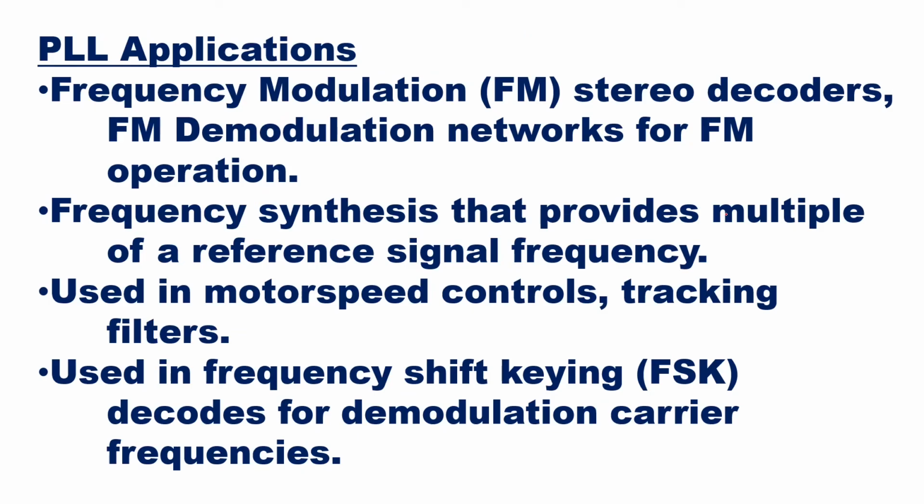Then we'll go to the applications of PLL. It can be used in frequency modulation, FM stereo decoders, and FM demodulation networks for FM operation. It can be used in frequency synthesis that provides multiples of a reference signal frequency. It can be used in motor speed controls or tracking filters. It can be used in frequency shift keying, FSK decoders, for demodulation of carrier frequencies. So these were some of the applications of PLL.